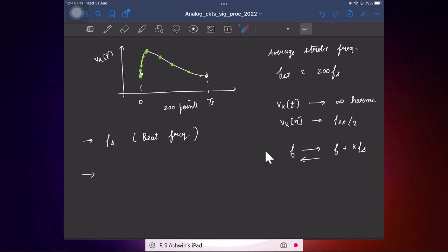Now, since the maximum frequency you can represent in your system is limited, that frequency from which you can consider the frequency translation will also be limited. Because the maximum frequency you have is related to Fst by 2, you cannot actually compute the frequency translations exactly beyond this frequency. Is that fine?